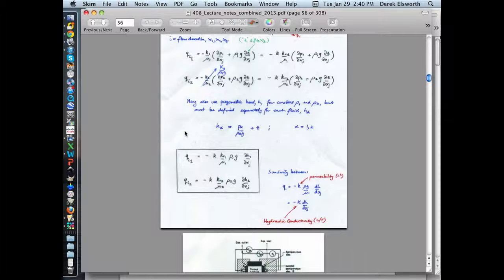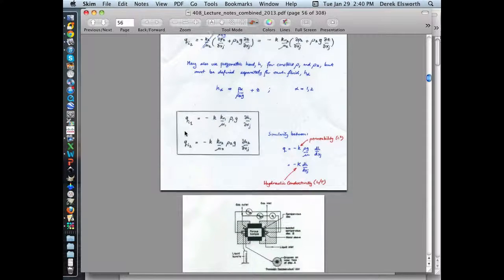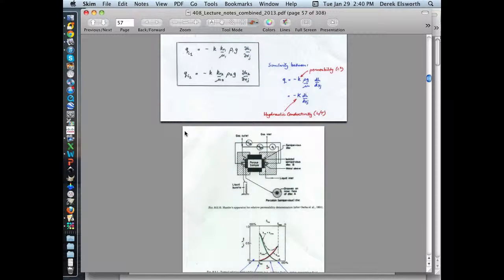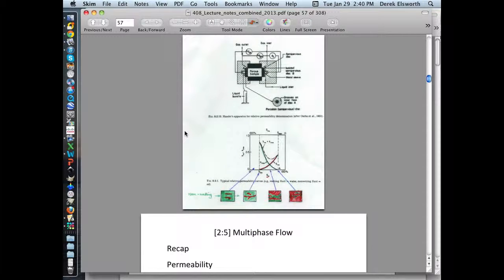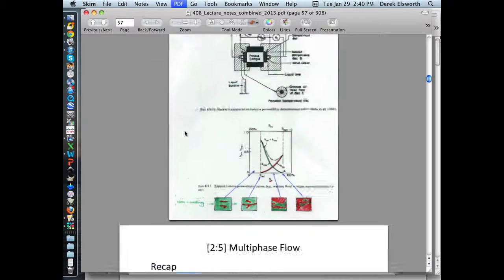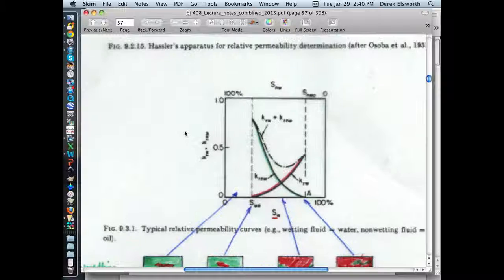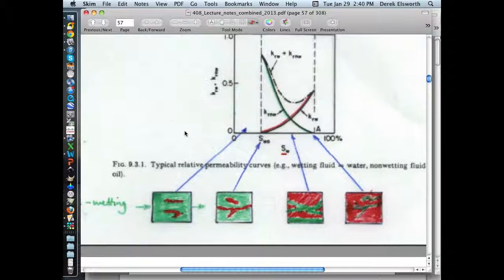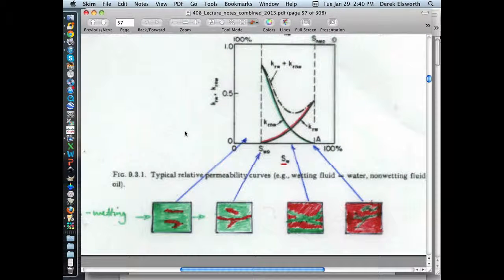And so the way that we deal with Darcy's law in multi-phase flow problems is to look at what we've referred to as relative permeabilities. And this is the key figure in all of this. I think pictorially it does a decent job in terms of how this index of relative permeability on the left-hand side, between 0 and 1, changes as a function of you changing the saturation.